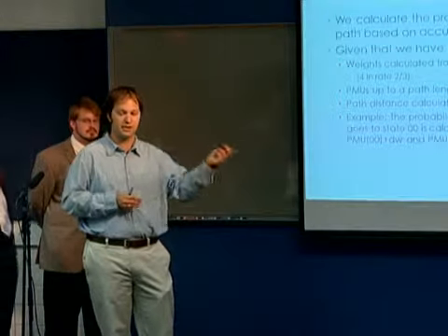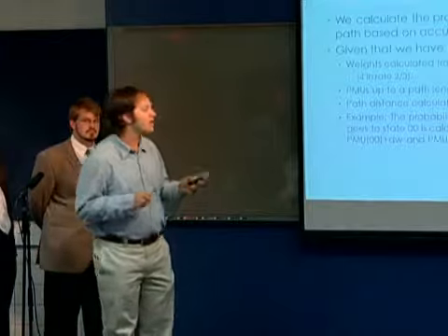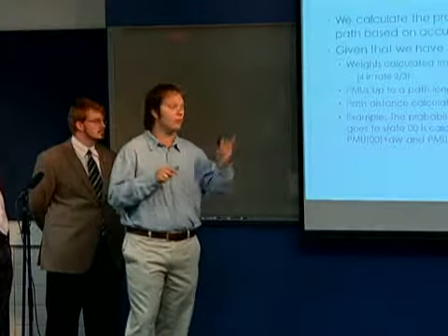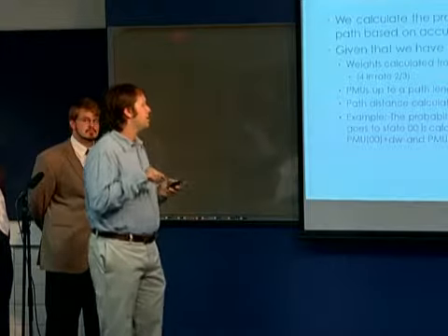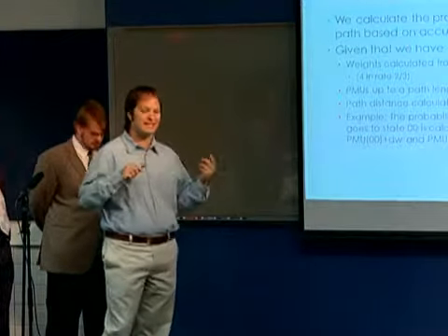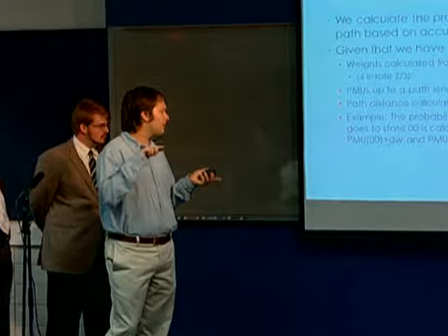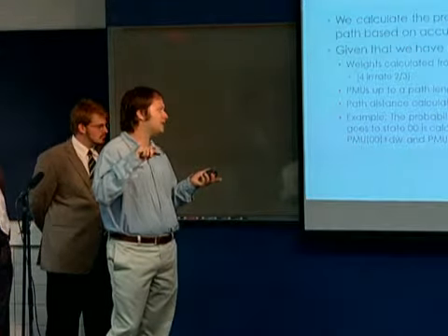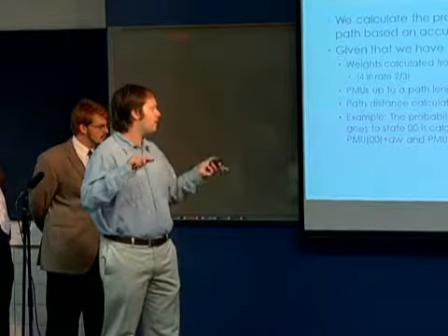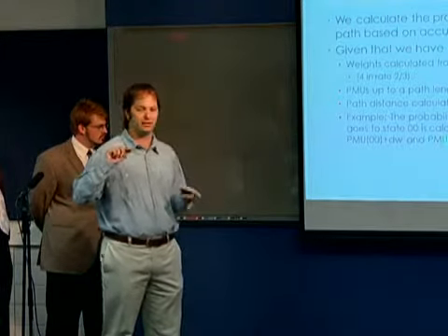So we calculate how it could have gotten to state 0. We take the accumulated path metric distance from state 00, add the distance that we find from the branch metric unit, and then we compare it to the other possibility.